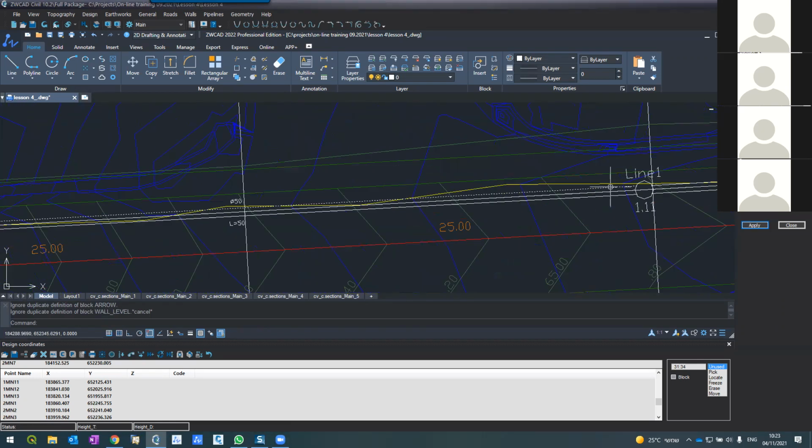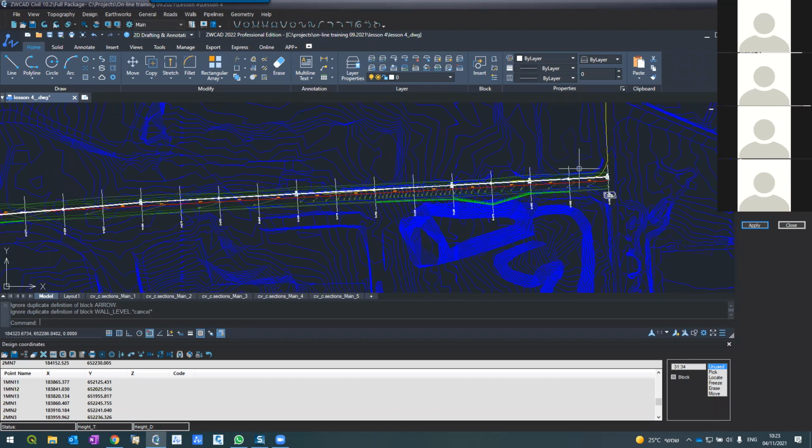So it's a new manhole, but the default was just with nothing. So let's put it also 150 by 100 and pipe diameter 50. Now, since the software didn't know how to call it, it just gave it a name, MN1 and 1.11, because it's intermediate between this one and this one.